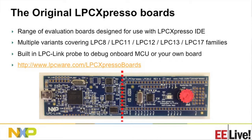Okay. The one difference between these two boards is that the debug probe on the old style LPCXpresso boards will only work with the LPCXpresso IDE. It's not compatible with any third-party toolchains.